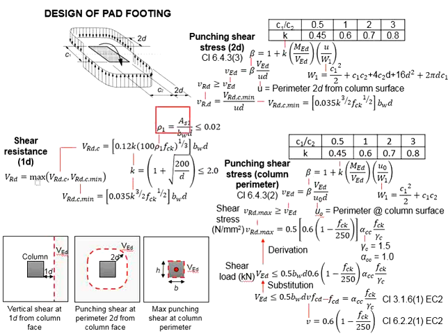While computing this number, you have to be careful with the amount of reinforcement bar used, especially when the As provided in the major and in the minor axis differ. Also, this As1 here refers to the actual reinforcement bar provided. You should use As provided instead of As required. As for the b and d here, you will have to look into the effective shear plane.